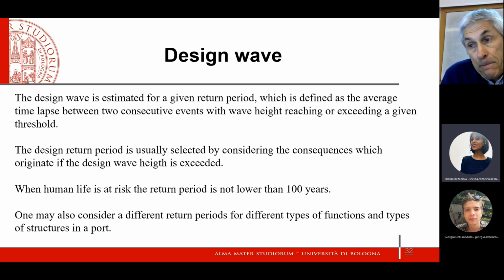So the return period is often a parameter for the project, for the design, which is often given by the law in force. So there are several regulations determining the return period for structures, infrastructures, several engineering applications. The return period is a measure of the risk. Let's say that it contributes to determining the risk. It's not the only driving force of risk.